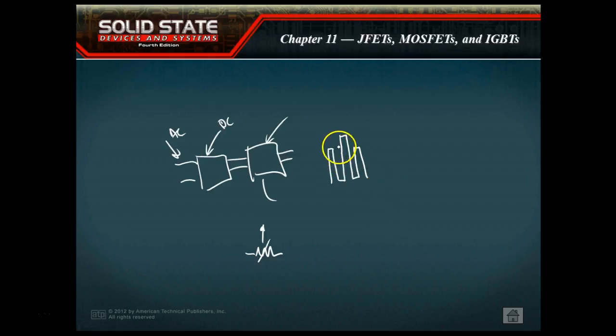And then I can change this right here. This right here would change the voltage. Or I could spread them out, and I could use this to change the frequency. But what we're doing is we're going to be operating off a positive and negative voltage. So it gives me the ability to use pulse width modulation on an AC motor. And what your AC motor is going to do, it's going to see AC. It's going to round that off.